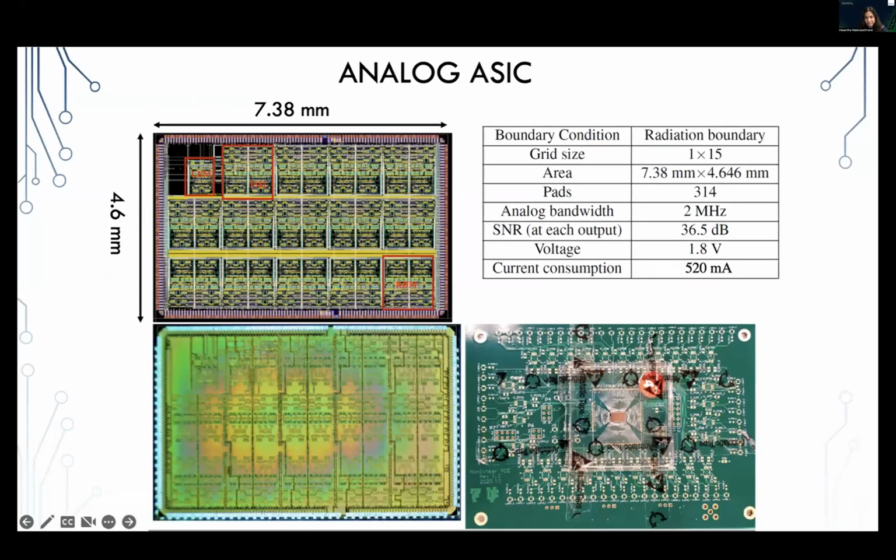So this is the analog chip, and the bottom left figure is the image of the chip under a microscope, and the top left is the layout of the chip. So actually, similar to a layout of a PCB, we can lay out a chip. The layout comes before fabricating a chip. So this layout consists of transistors, and the outer area consists of pads. These pads are for connecting input-output pins and power supply, power and ground connections.